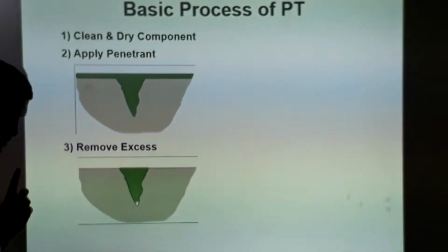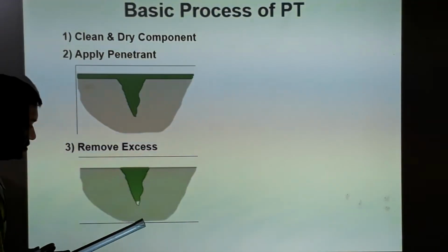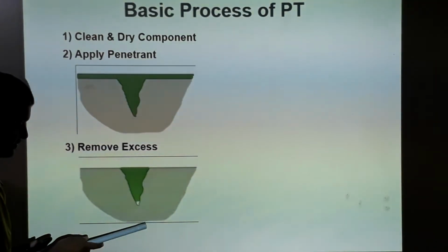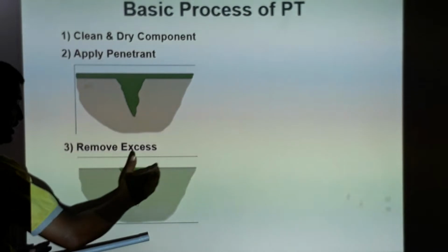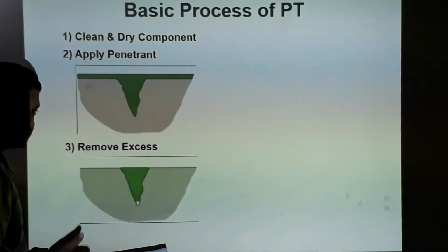And you need to remember the small things. See, a small amount of penetrant also gets evacuated from the bottom portion of the defect. This much penetrant will also get cleaned up due to the pressuring force of water, in the case of water washable penetrant.